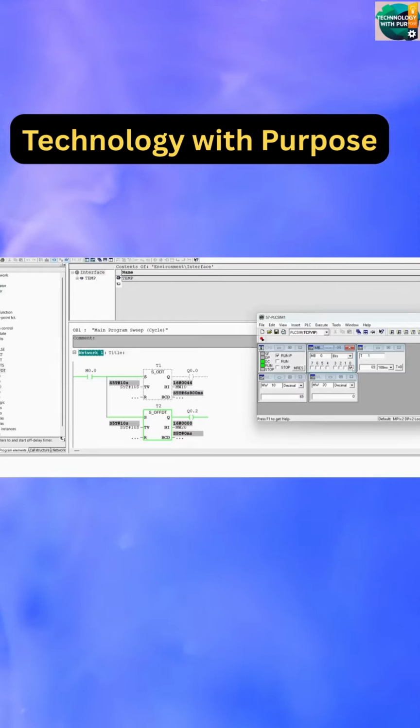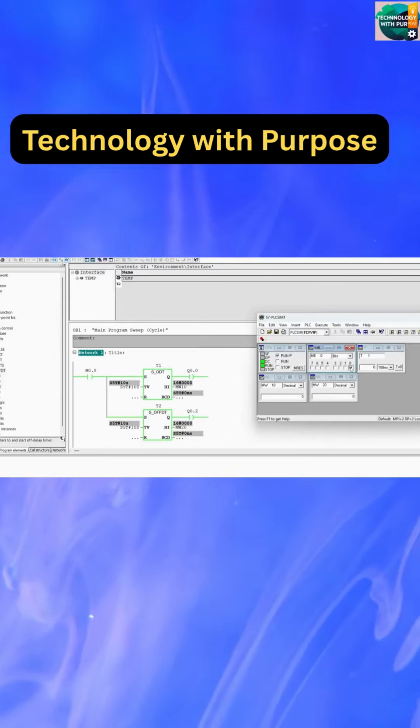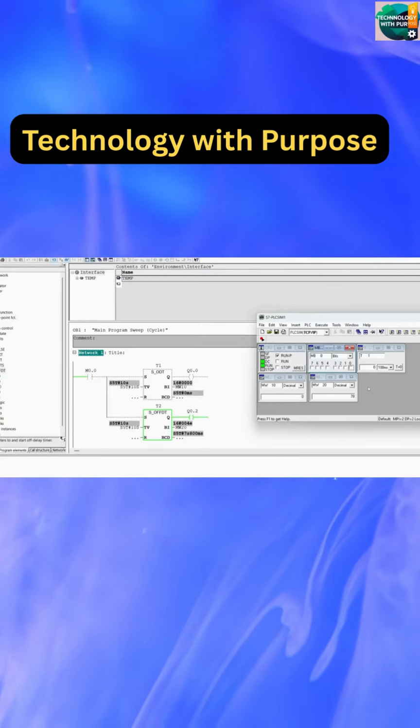Now you can see that T1 has completed its counting, and after counting is over, T1 has turned on its output, but T2 has neither started its counting nor turned on its output. Now let's turn off M0.0 and see what happens.